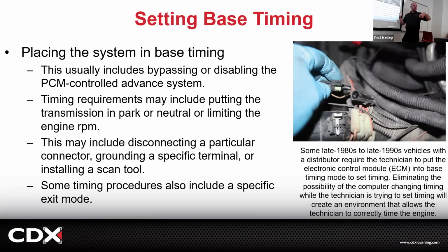You hook it up to cylinder one, you hook up voltage and ground, and you literally shine it down there and you see where this little line shows up. And if you turn the distributor, it'll move the flash one way or another. And you're just literally using this Duck Hunt gun. It's very mechanical. It's cool. You guys will do the discussion. There's a bajillion videos on setting timing.